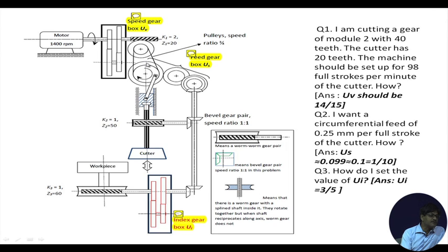Coaxial with the larger pulley, if you look at the top, we are having a gear. This gear is connected with a number of gears and it makes up a gearbox, though not exactly shown in a proper rectangular box. This serves as the feed gearbox. So, we basically have a bifurcation here. Just after the speed gearbox, there is a bifurcation.